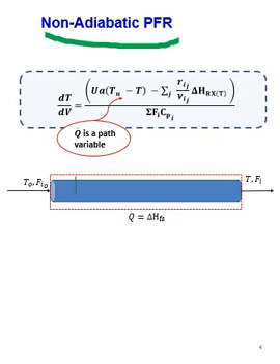Because I have a temperature variance over the length of my reactor, the rate of heat transfer in that specific slice will be a function of the temperature in that slice. So there's no possibility of getting a straight line relationship, and when I have a non-adiabatic PBR, I must use the differential equation for change in temperature with volume to express my energy balance.